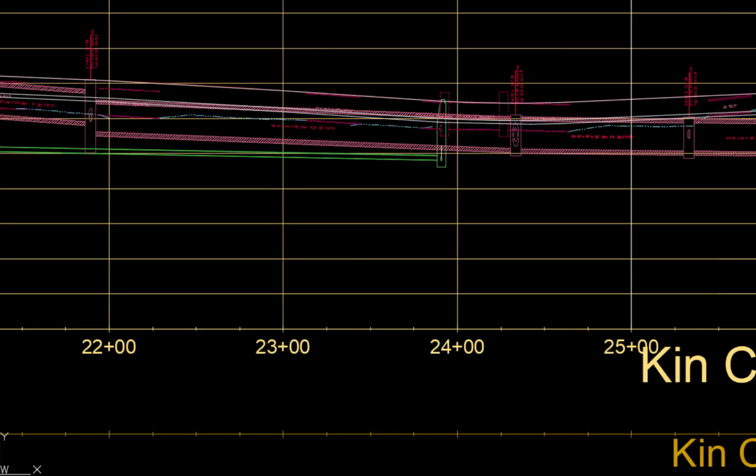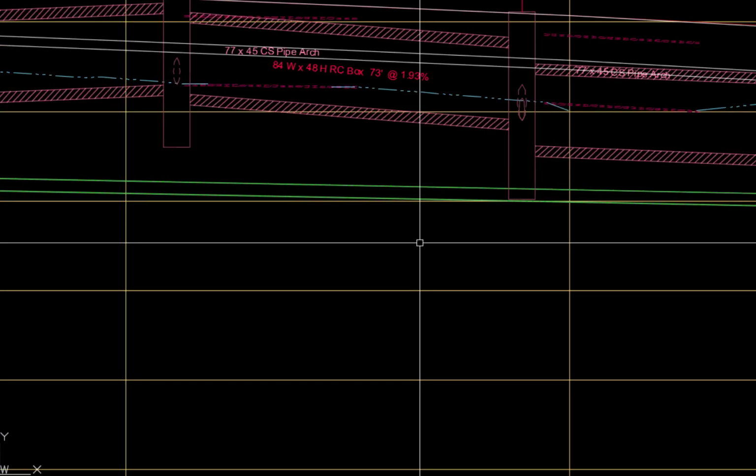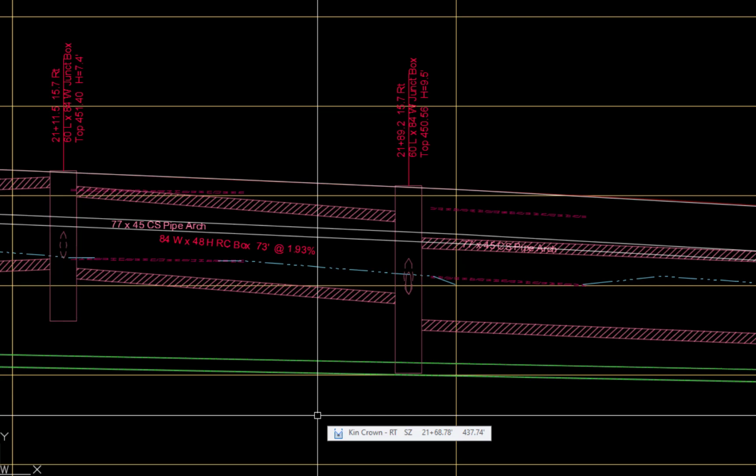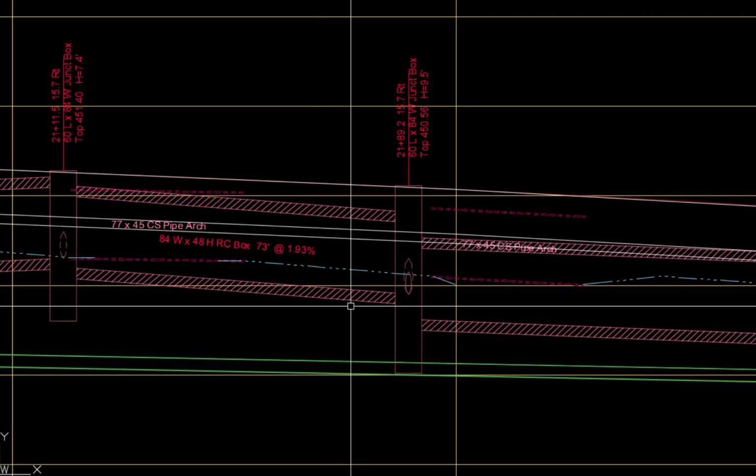Use the 3-foot depth layout lines to continue adjusting the elevation of the pipes and structures. The invert of the inlet pipe to a structure needs to be slightly above the invert of the outlet pipe. Pick the pipe and use the end glyphs to visually move the pipe vertically to the desired location.